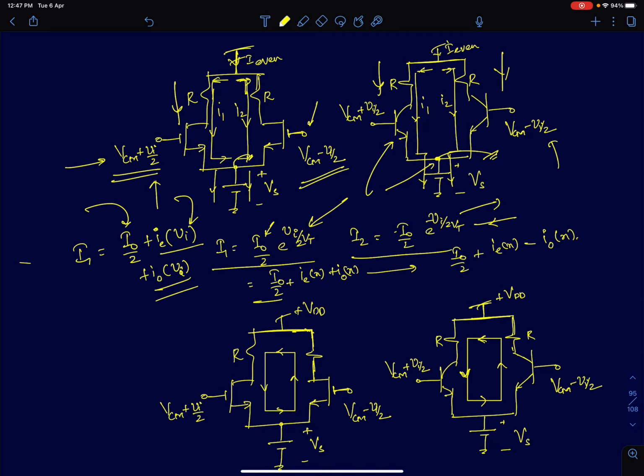If I assume that condition, then one very important part to understand is that the input is applied symmetrically to both the transistors. If I apply Vid as the differential input, which is equal to Vi in this case, half of it will appear across one transistor and the other half across the other transistor. The interesting thing to note is that the polarities of both the VGSs are exactly opposite. I'm stressing the point that the input will distribute symmetrically.